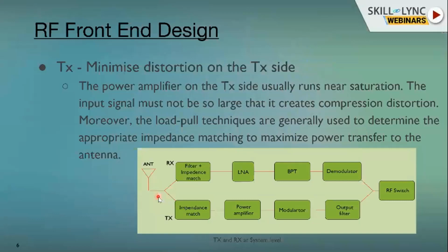But when it comes to active devices, particularly an amplifier or power amplifier, their behavior changes quite a lot over time and also over frequency. Let's say you are designing a power amplifier which will work at 800 megahertz. It will be way different from a power amplifier designed at higher frequencies, because of the stringent rules, the microsystem or fabrication restrictions, and also the cost.